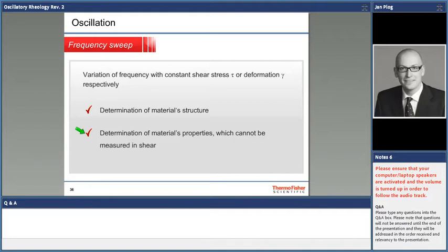In principle, we can measure the elastic response in rotation when you have a rheometer that is capable of normal force measurements. However, for most viscoelastic fluids, polymer solutions, polymer melts, whatsoever, you will not be able to measure in rotation because of the effect that we call the Weissenberg effect. When you shear your sample in the gap of the rheometer, the sample will leave the measuring gap at one point or another, usually very, very early, because your sample does not want to be stressed. Okay, always keep that in mind. Your sample does not want to be stressed. It tries to escape the stress level, and the only way the sample can is by leaving the gap.